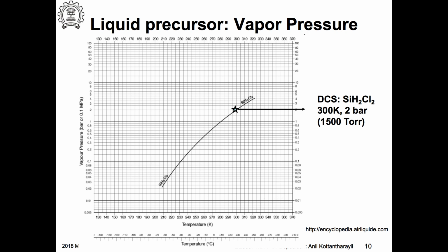That assumption was not correct. So we had to buy a temperature controller, a special type of cabinet in which you place the container of this POCl3. Because of safety issues, it comes with a lot of valves and so on, so you need specially designed heater cabinets to house this.